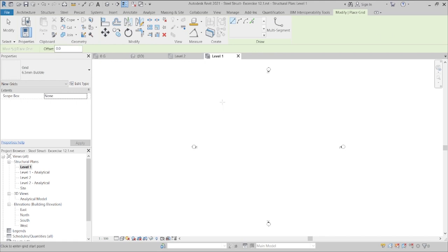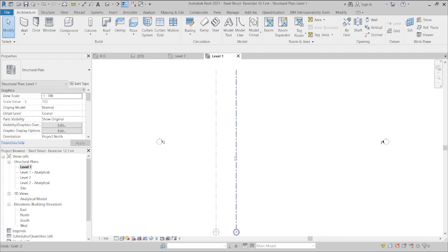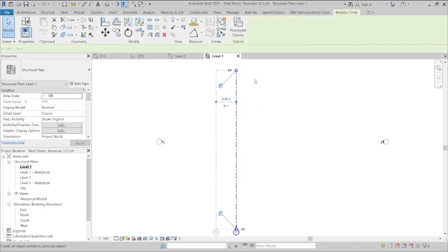So we can come to level 1, and say, let my grid be that way. And then come 450, just type 450 if it's difficult to snap. Click OK. Come here, click again, go back to your level, 450. Just click and say create similar.